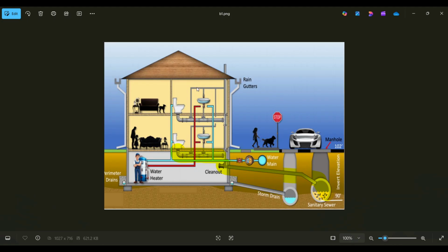And then the next system we have is our sanitary water system. Can you see here we have a water closet here. The waste from this water closet gets transferred using these pipes. So in this example, can you see we have three sorts of pipes, or DWV pipes. Drain, we have drain pipes. For example, if we have a shower here, the water that drains from the shower gets transmitted into a drain pipe.